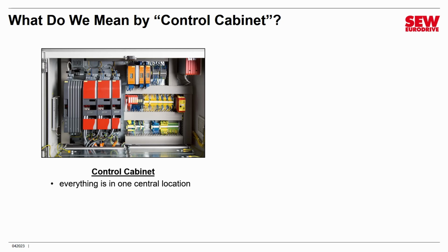But in general, they stay in a control cabinet. And the reason they do this, of course, is for protection, because many industrial environments have all sorts of threats to electronics, like solids that could get inside, dusts and other things, and especially liquids like water or other materials that could get in and wreak havoc with the electronics.